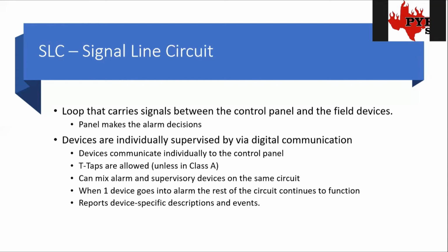You're not able to just use the one circuit to pick up both devices because you've got two different types of signals. On these SLC, we can pull just the one SLC loop in there, and it grabs both monitor modules on that primary side, and it can mix the alarm and supervisory devices on the same circuit. So that's another big difference between SLC and IDC.